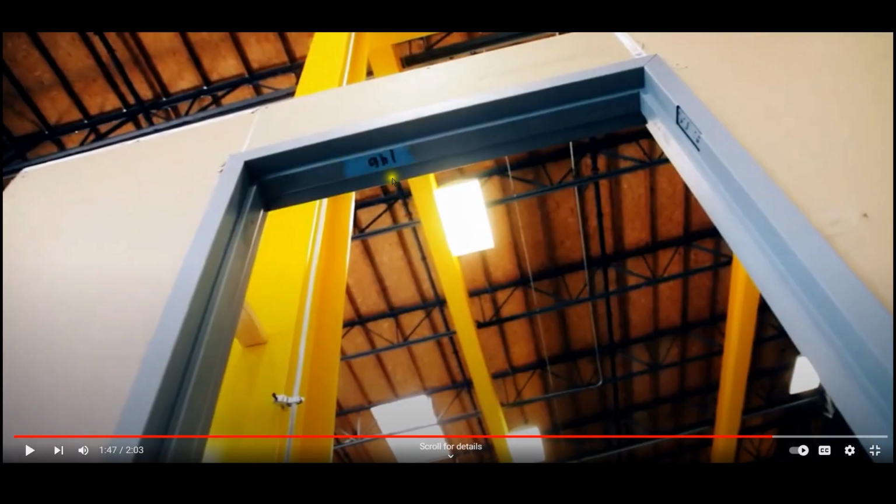I'm not sure if that's, hopefully that's blue masking tape. Never, never, never use a black magic marker on the hollow metal frame, because when they prime and paint, that will still bleed through. If you do it, you can expect the client to call and say that he had to sand all that off.